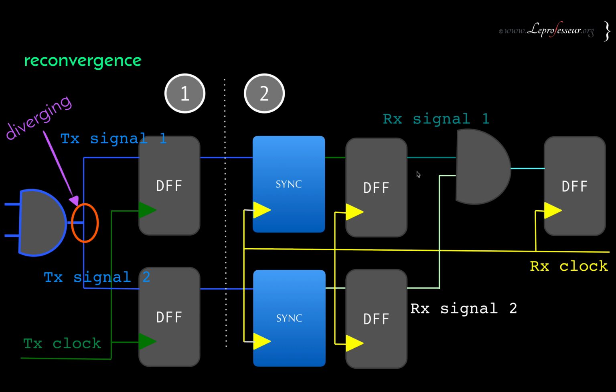There are different techniques one can use, either to move both of these signals into the first clock domain, and pass only one signal to the second clock domain. So always remember, one signal or fewer signals passing to the other clock domains are good. If they are converging somewhere, we need to be very careful.